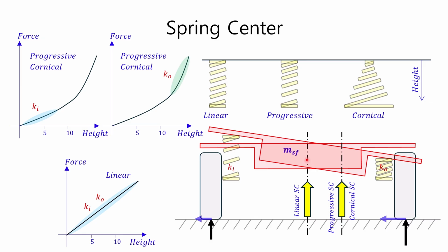However, if the lateral force increases, the spring center moves outward during the turn. When a large lateral force is caused, the spring center can change depending on the size of the lateral force, so the term incremental spring center is used to distinguish it from a general spring center.